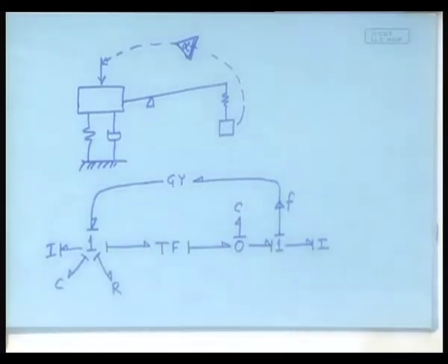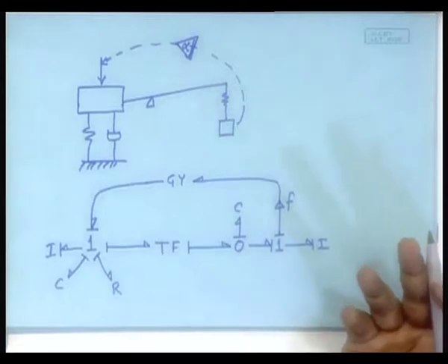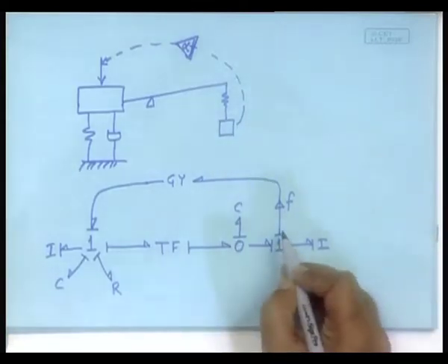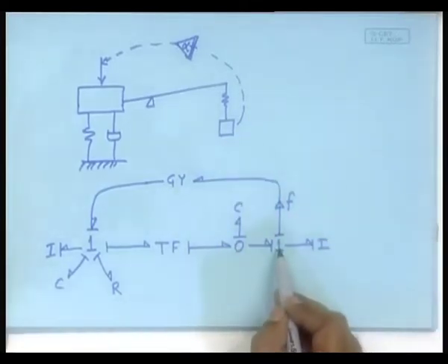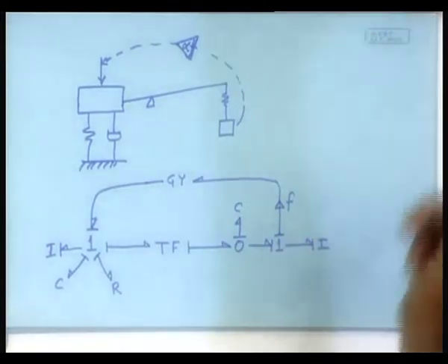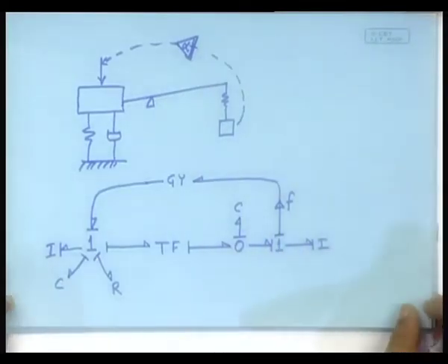Sir, in this case, when we are putting the observer which is giving the flow information, can't we just blindly put the causality stroke here? It is after all taking the flow information. Yes, you can do that. So, his question is, can't we blindly put the causal stroke here? Yes, you can, because if you are trying to observe the flow, it must be connected to a bond where the flow information is already available, and that happens in a one junction. So, it is already there.